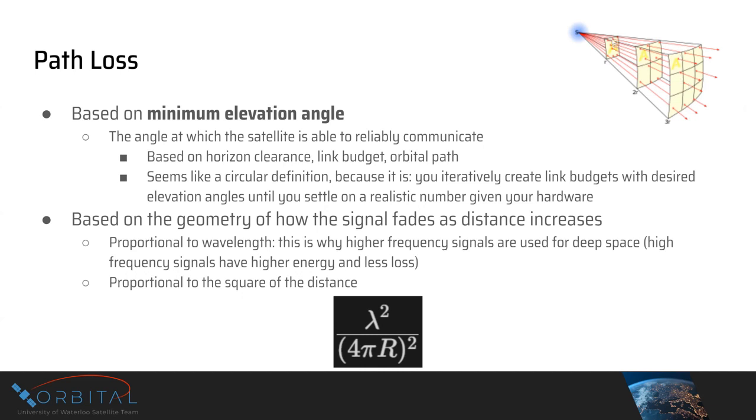You can see as your signal disperses, the conic angle stays the same, but the area that you cover based on that angle gets larger. A loose way of saying it is more area and the same amount of signal, so you have a lower signal strength. So that's an intuition as to how path loss works.